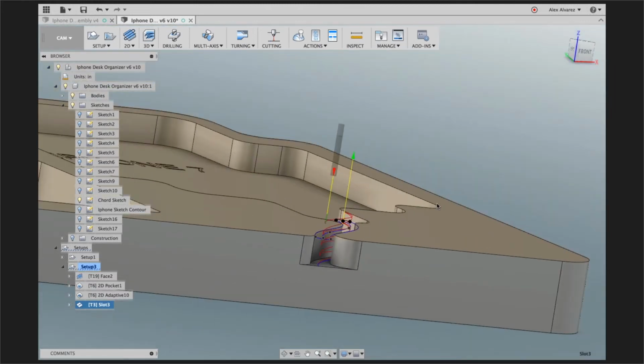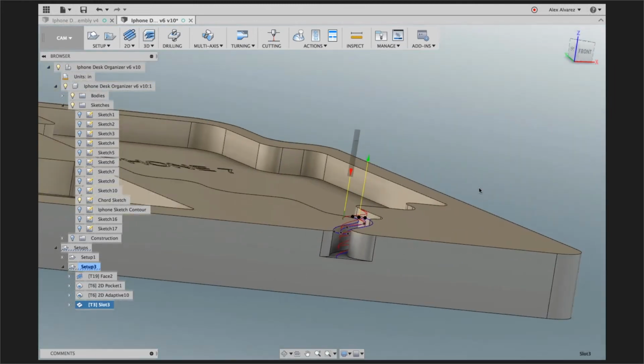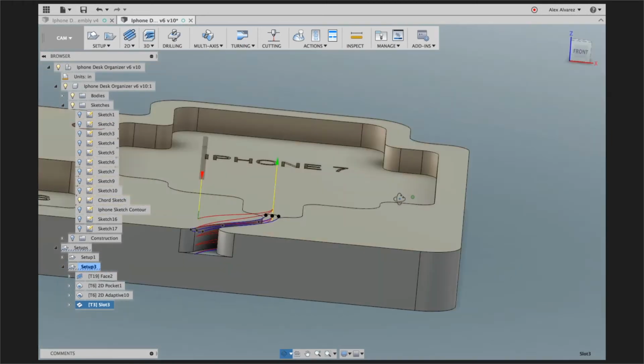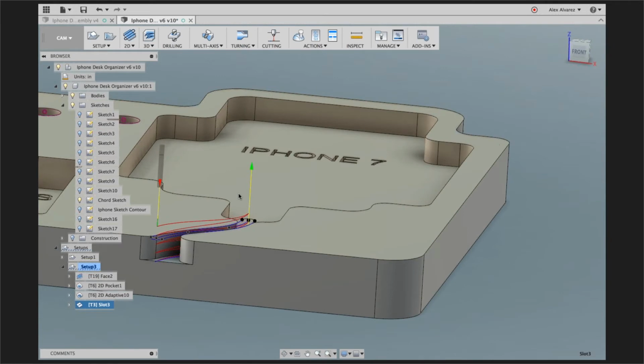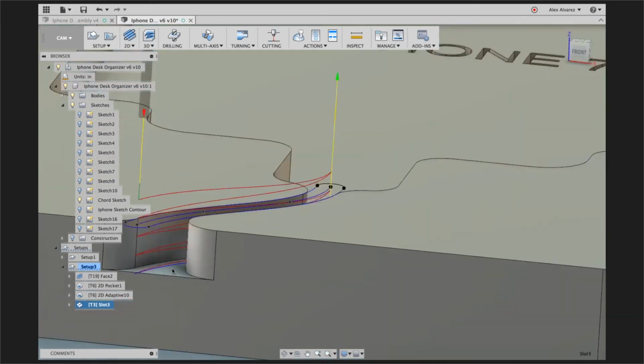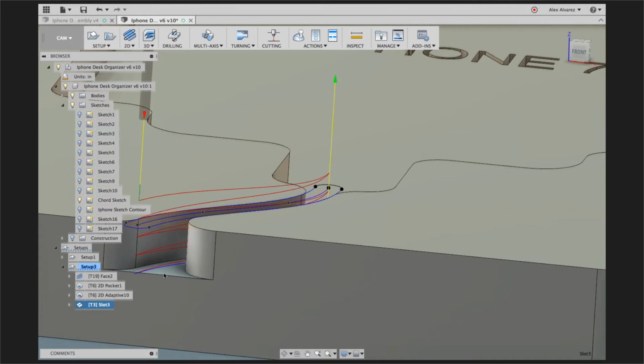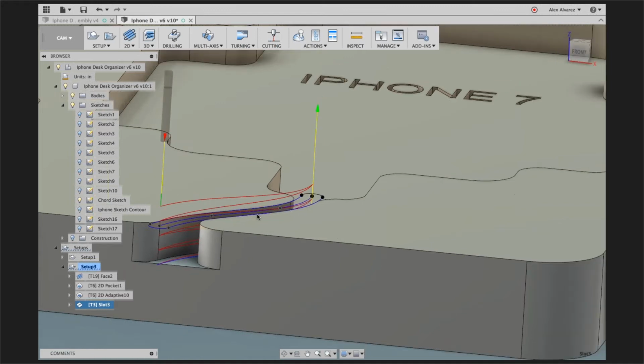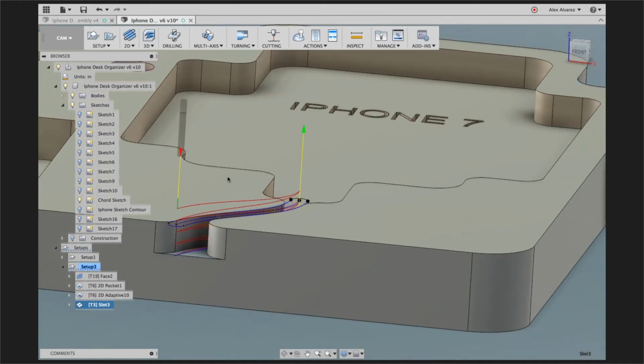Now what's neat about this, as Brian was saying earlier, this is an integrated CAD/CAM software. So what does that mean, right? Essentially, if you were to change the height of this face, you can expect Fusion to parametrically change the way this toolpath is running. So instead of machining up to this face, once you make a change to the model, it's going to machine up to that updated depth that you have created. So that's nice to have. It's going to save you a lot of time instead of having to actually select the face again and create that toolpath.